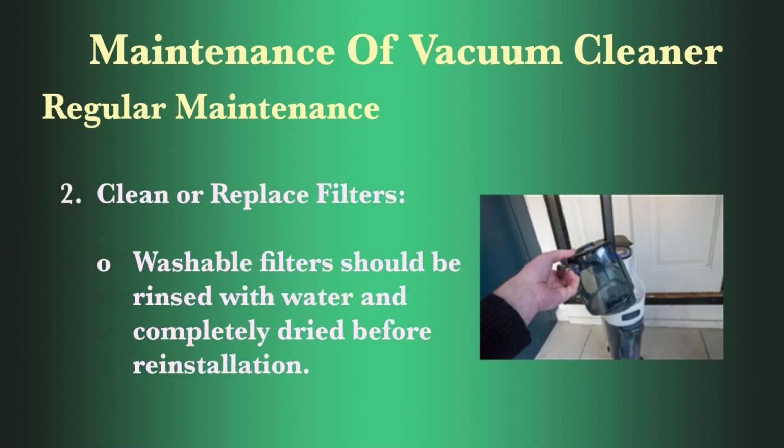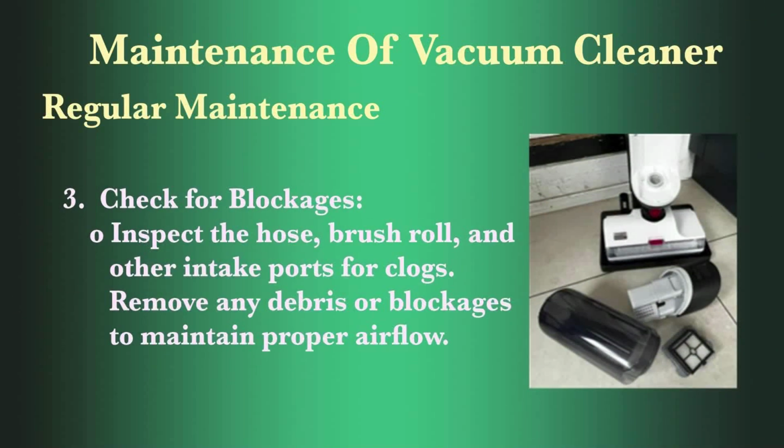Then there are washable filters. Washable filters should be rinsed with water and completely dried before you reinstall them. Now number 3 is check for blockage. Inspect the hose, brush roll and other intake ports for clogs. Remove any debris or blockage to maintain proper airflow.